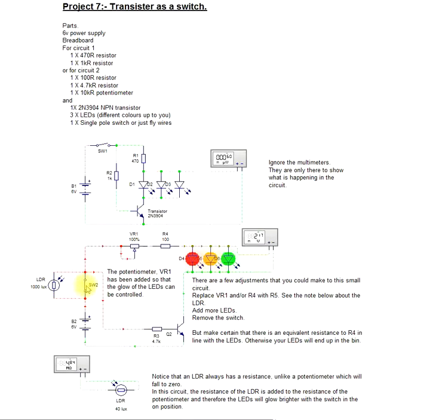Now if I remove that power, the power then is based solely on this LDR. Now we change the value of this LDR, only a small amount in this particular case. It will turn our LEDs off or back on again. Very simple, very straightforward. If we were in a dark place, we could have it so that an LED was lit just to let us know that it is light outside or something along those lines.